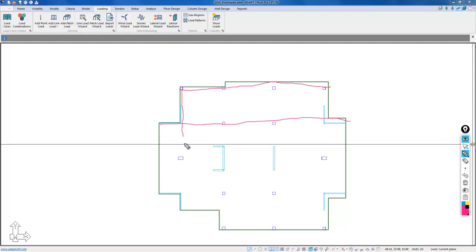then we're going to run distributed cables down, and I'm basically just going to run them along this frame line. So we're going to have a reverse parabola here, a reverse parabola here, and then we're going to use just a cantilever down shape and anchor them along behind this line here, this frame line. So that's how we will model the tendons. Again, we're only going to set up strips in this region anyway, because that's our area of focus for this particular evaluation. So let's do the banded first.